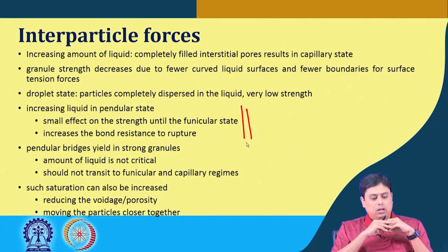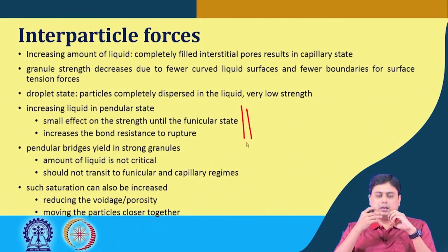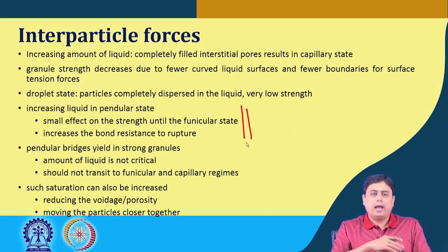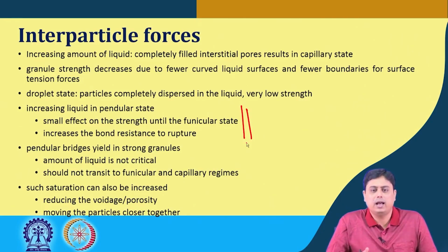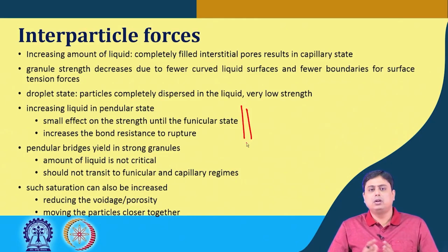Therefore, it finds relevance in the granulation process, because in granulation what we try to achieve is the agglomeration of fine or smaller particles using agitation as sturdily as possible. That aggregate should be able to withstand a certain amount of attrition or external forces in order to not break again.